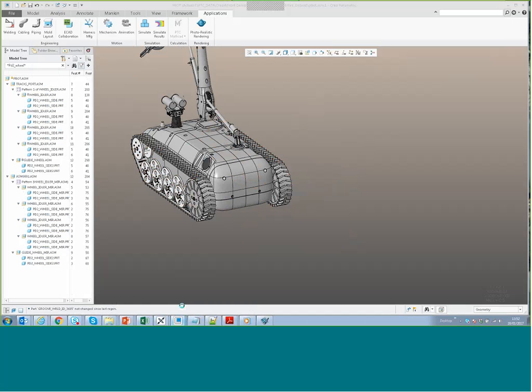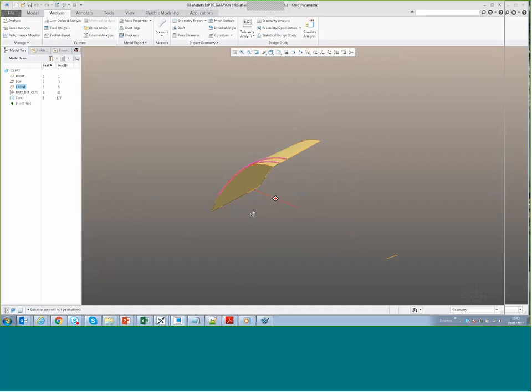Next thing I want to show you, which isn't perhaps covered so clearly in the slide deck, is a lot of the functionalities surrounding industrial design applications. So something we did in Creo 4 was implement G3 connections. Now, for those of you who don't know, G3 is like the holy grail of doing A-class surfacing. So typically, what we had in the past, so if you look at a fillet is tangent, and you can actually see a hard edge from a fillet between something that's curved and something that's not curved.